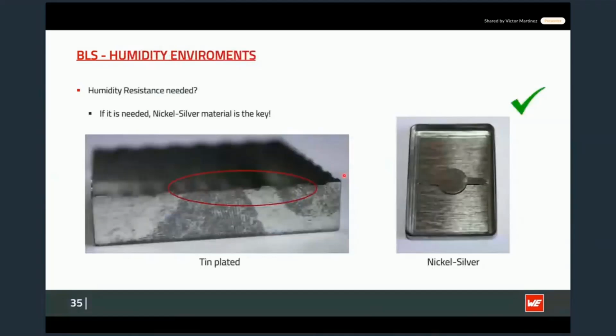Then some tips about shielding cabinets. One of the first things you need to have in mind is that at the end we have a metallic piece, and normally a metallic piece, when you place it outside, like a metallic fence or a metal pole, gets oxidated just by the humidity of the environment or maybe because of the saltiness of the environment. The standard cabinets are normally made of tin-plated steel, and tin-plated steel, especially on the edges, gets corroded or oxidated extremely easily.